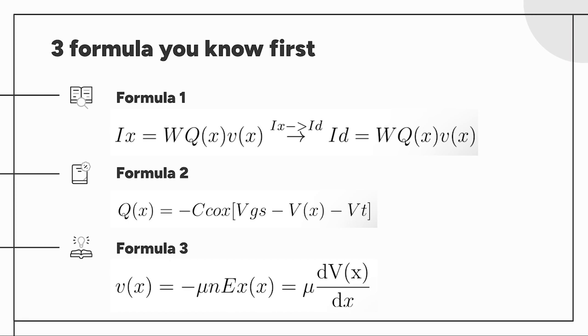This expression is derived from the expression that Q equals CV. This formula was also introduced in the Physics 2 subject. In the above equation, C is an electrical capacity, so you don't need to deal with it in detail. And to explain the voltage part in detail, Vx is the voltage at X position and Vt is the voltage consumed by forming the channel itself.